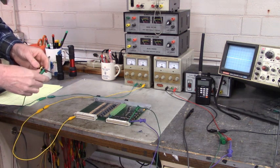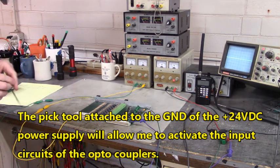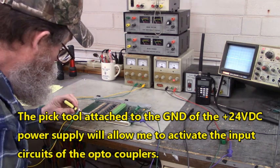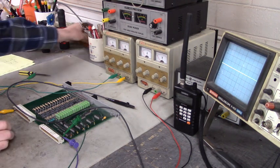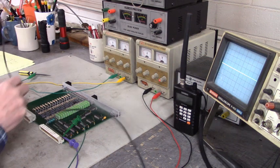I'm going to use a pick tool to probe the inputs. And as I probe the inputs, as I pull the inputs to that 24 volt DC ground, the outputs will go low on the output side of the opto-coupler.